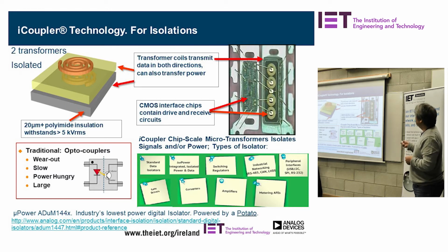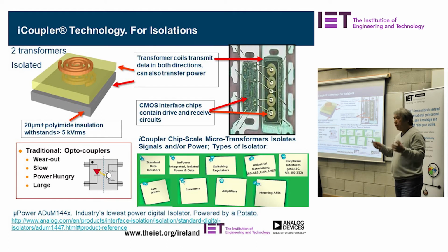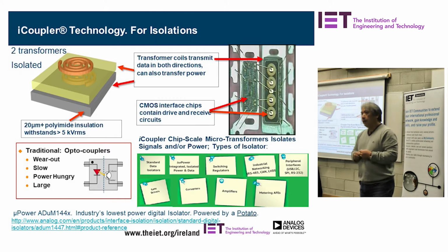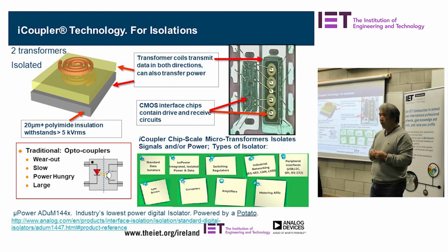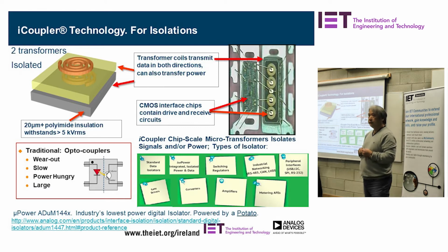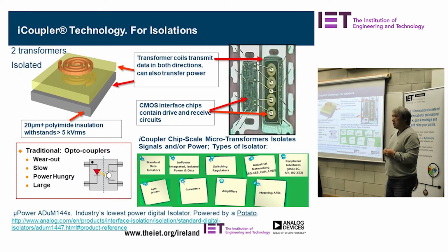And this is one of the ICs. Here the transformers are completely isolated, transferring to this IC on the other side. So it's completely isolated. You have a lot of applications here: industrial, metering, interfaces, amplifiers. Instead of using a bulky transformer, you can use one chip to do the same job. What about speed? Yeah, they go very high. Some of them go up to mega and tens of megahertz now. They're very high speed, and they keep advancing all the time.